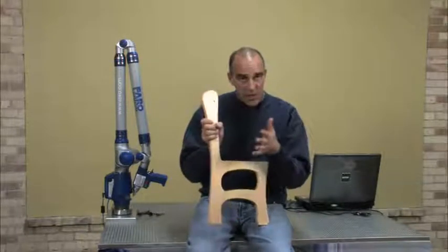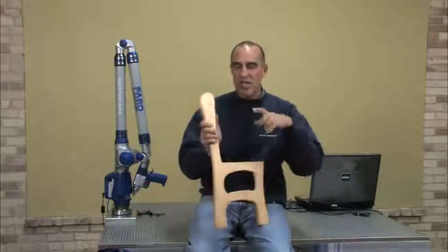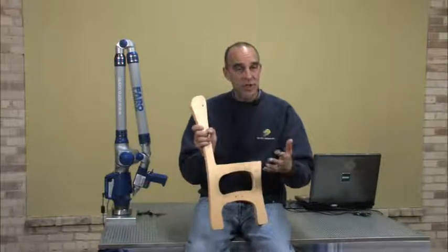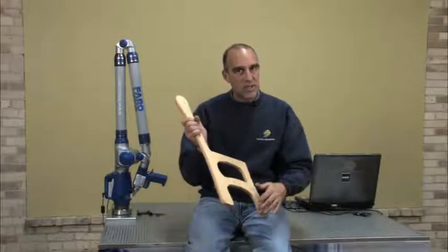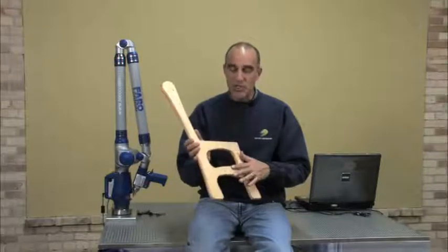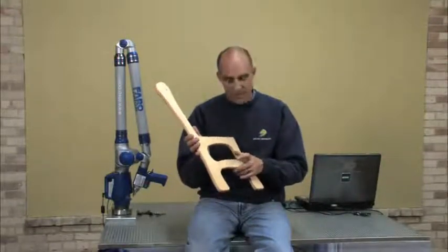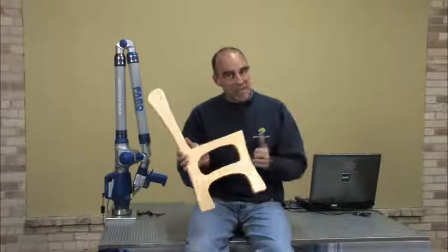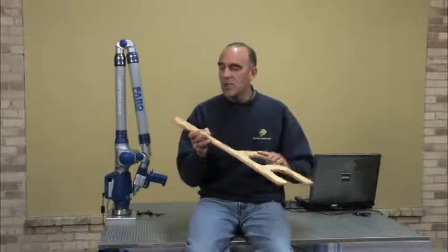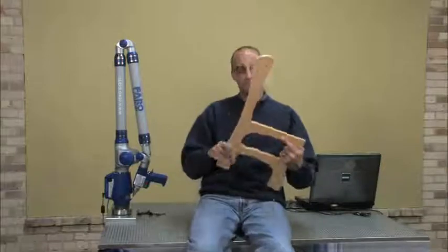But my client needs to know exactly where the center point is so that he can set up a drill jig or a drill fixture and pop these holes in his manufacturing process. So that's a great example of how to use a planar point to solve for the center of that. So we're going to jump into an SAT file, and I'm going to show you guys how to do planar points. So come on in.